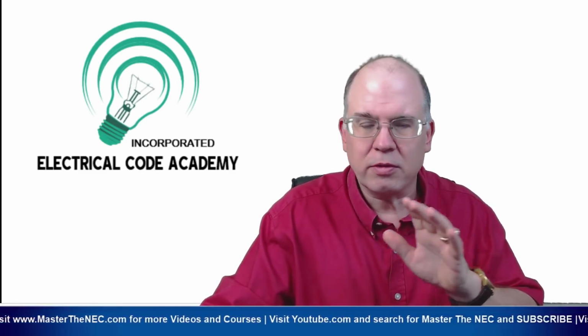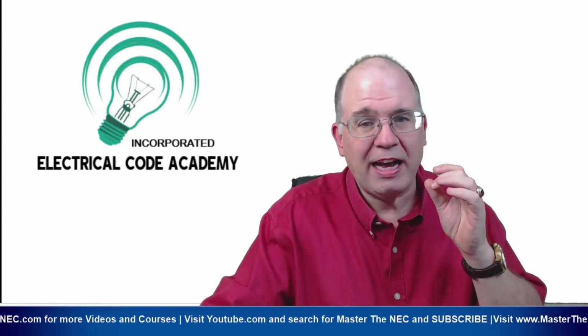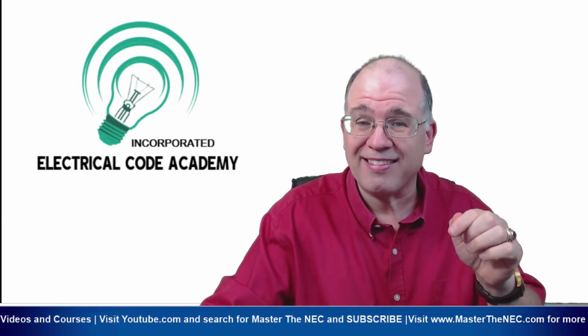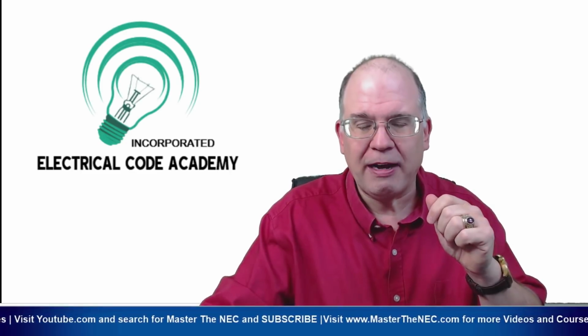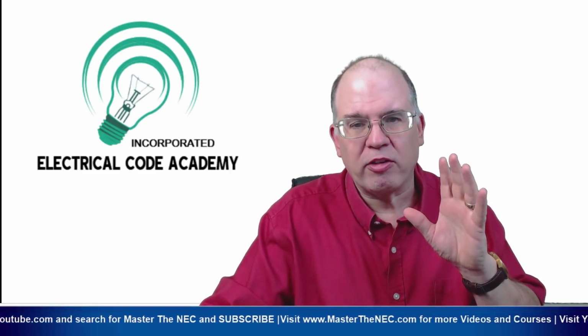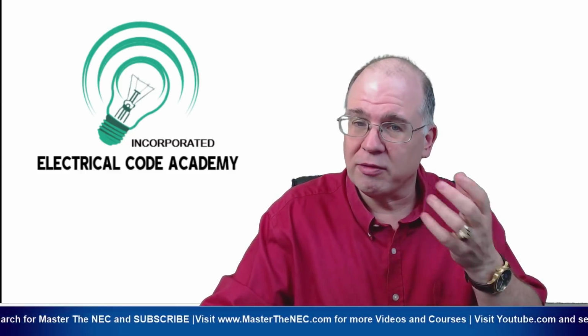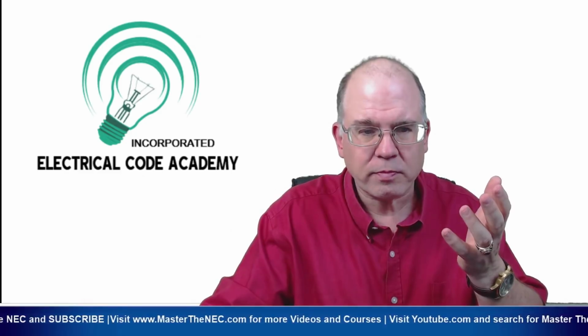Keep it that simple. Don't get too far ahead of yourself. We've got terminations to worry about. We've got overcurrent devices to size to make sure we protect those conductors at their ampacity. Even at their new ampacity after adjustment and correction, we have to verify. We're just dealing with breakers now. But remember, when we start sizing it, we've got to make sure that everything falls in place. I just like to start at the breaker and give you some clarification.